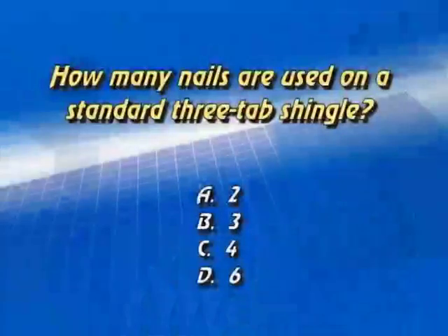Number 44. Which of the following building materials offers the most insulation? Wood, brick, concrete, or aluminum? Now, aluminum is a great conductor, not only of electricity, but also of heat, so that's one of the worst insulators. Concrete and brick are pretty dense, and they will also allow transference of heat, although slowly. Wood is not nearly as dense, and of those four, wood is clearly the best choice, so the answer there would be A.